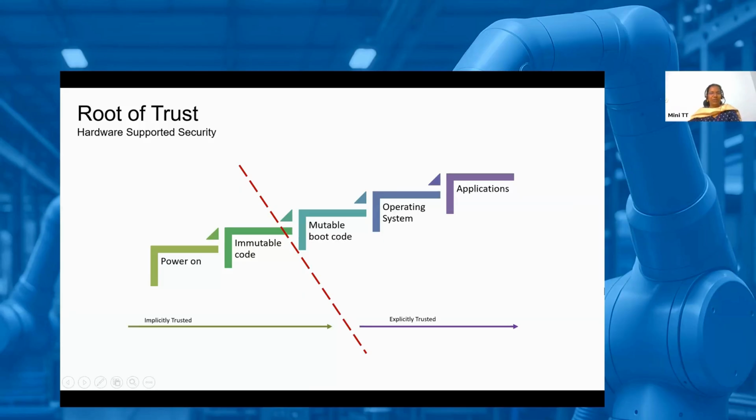So we will start off with one fundamental assumption that we have to achieve if we want secure physical devices. We need to have something called a root of trust. A root of trust means that when you boot the device, the firmware gets loaded one by one. In this process, how do you know there is a root of trust as an anchor so that every other firmware running on it is good? Typically, this is a hardware-supported way of achieving security of the physical device. This root of trust will make sure that you are not allowed to run any firmware component, whether operating system, mutable code, or application, anything, and I'm coming to UEFI secure boot and those kinds of topics. It's not possible to load any mutable firmware unless you are able to verify that it is genuine. That is what we will achieve by this root of trust.